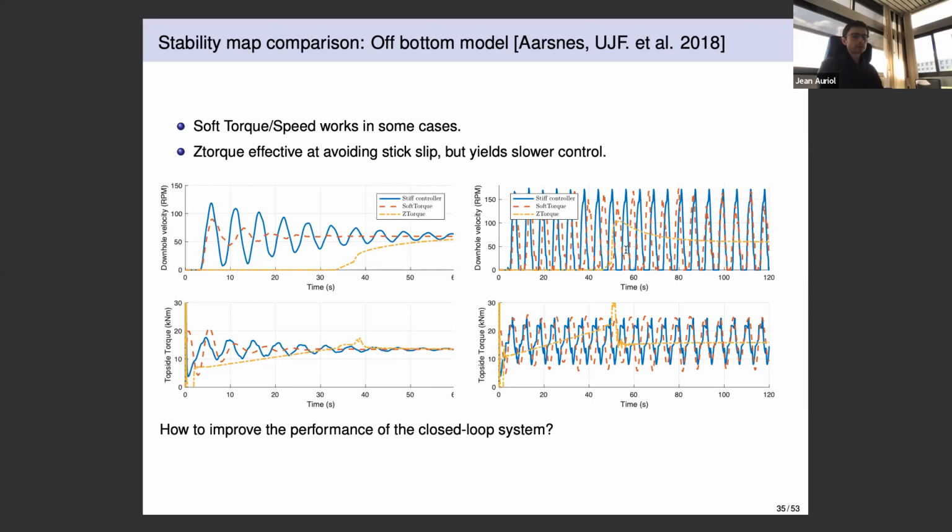Okay, constant value. Because I've seen quite a lot of torsional stick slip which comes from when you go to high frequency or high RPM, because the top drive cannot drive the drillstring anymore in ERD wells. That's actually relatively important for some of the things we do, because we have seen that going into higher RPM before converging back to your nominal value really helps. But you're right, it requires relatively high RPM and torque at the startup, so this is definitely something that we should include. I guess Paul knows everything about the ERD wells, but in the ERD wells you are really at the limit of the top drive, and these limits of what the top drive can provide are a very easy source of oscillations.